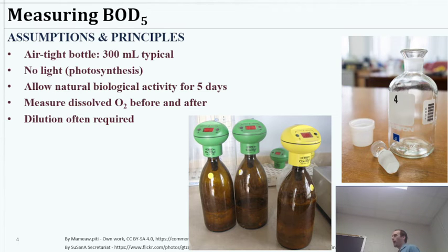Now, if you have a sample of wastewater, let's say, or particularly dirty lake water that you're studying, I say dirty, but particularly rich in organic matter, you might have a situation where the amount of oxygen that's just naturally dissolved in the water at saturation is not enough to supply enough oxygen for the bacteria to do their thing for 5 days, right? You might have way too much waste.